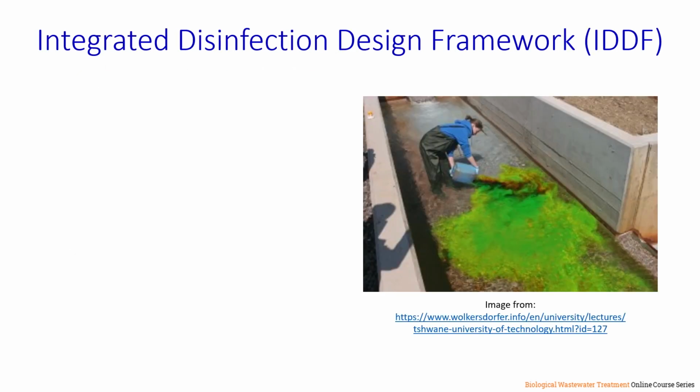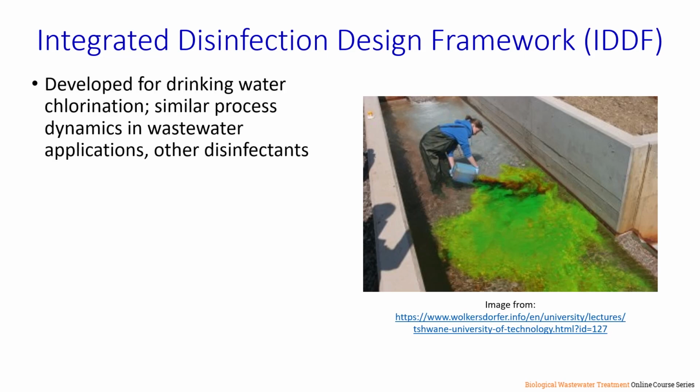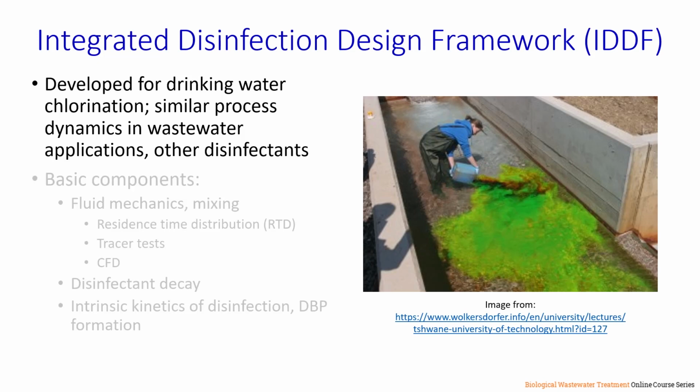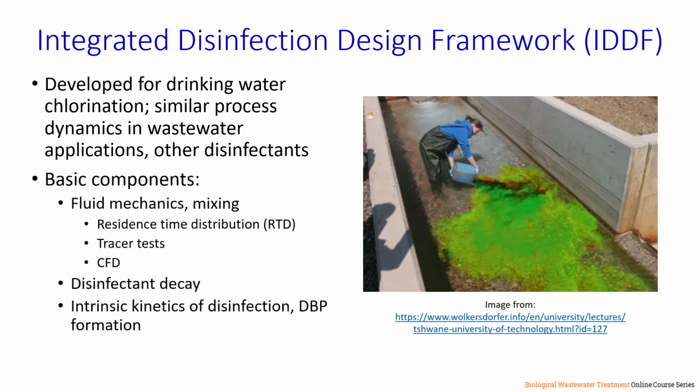An important development was made about 10 years ago with the development of the so-called Integrated Disinfection Design Framework, or IDDF. This framework was developed for drinking water chlorination, but the idea is something that can be extended to other disinfectants and other applications. The basic components of the IDDF include a description of fluid mechanics and mixing. Generally, this is done to characterize the residence time distribution function, and this can be quantified using a combination of tracer tests, as illustrated in the image on the right, or computational fluid dynamics, or both.